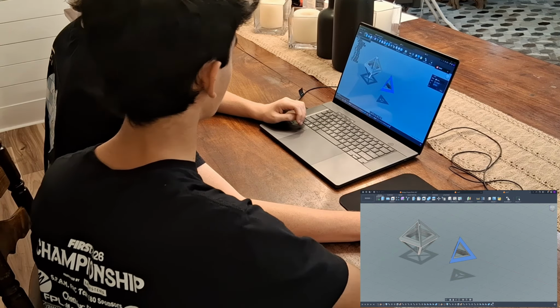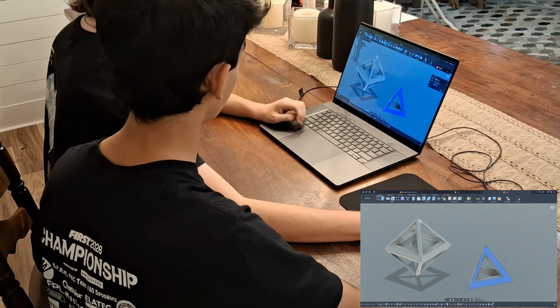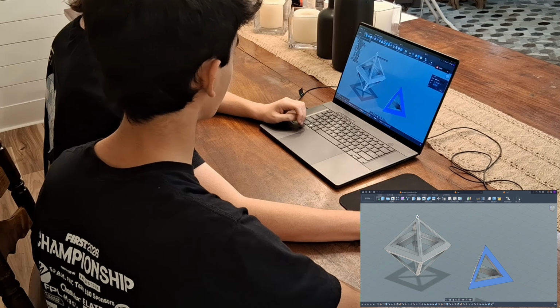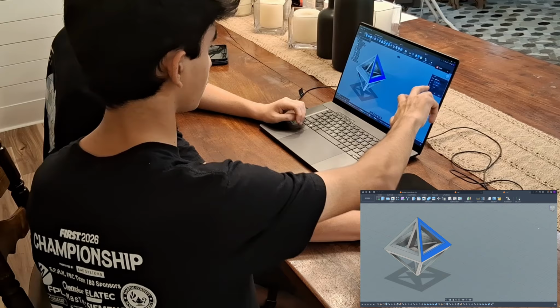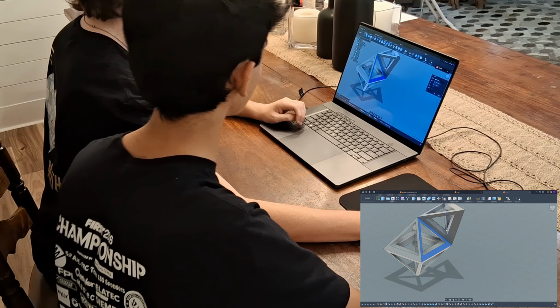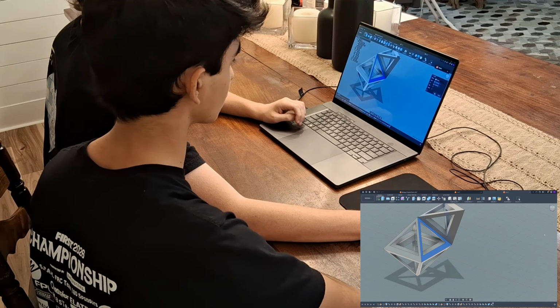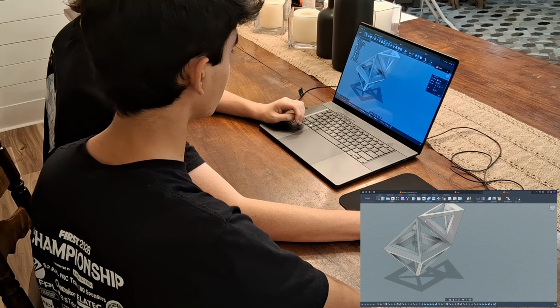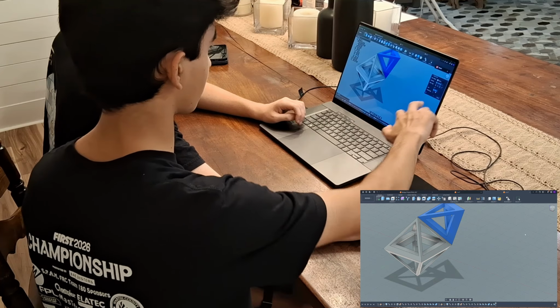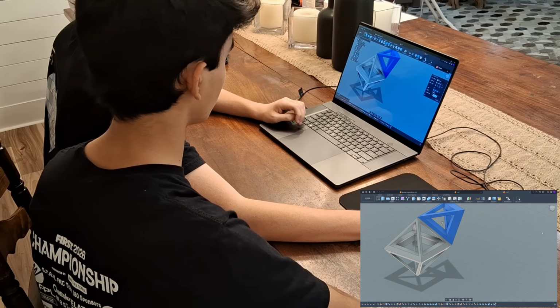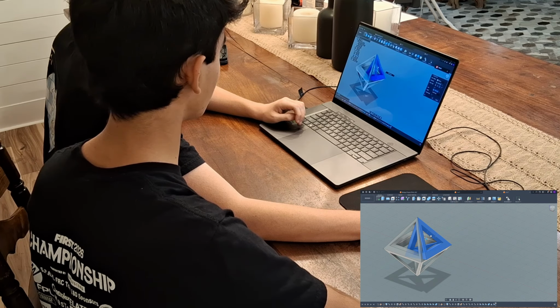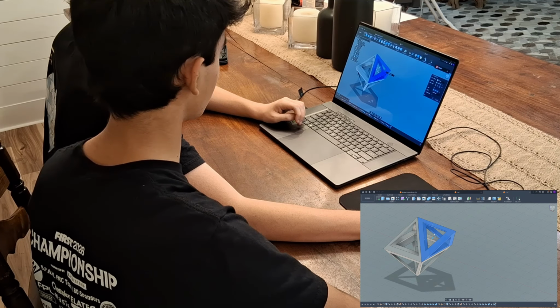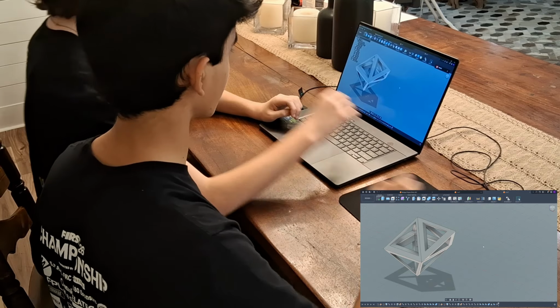Yep. So you can scroll in a little bit, and then yep, hold Control. There you go. Yeah, click on that. All right, nice. And then you can just use the flip tool because it's pretty inconsistent. All right, now just click OK, and then how are you gonna rotate it? Move. Yep. Use your move command. Yeah, select the body, and then select your axis that you rotate. And then just rotate it down 110. There you go. All right, nice.